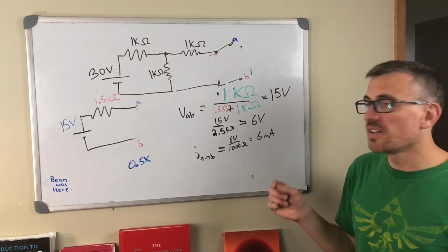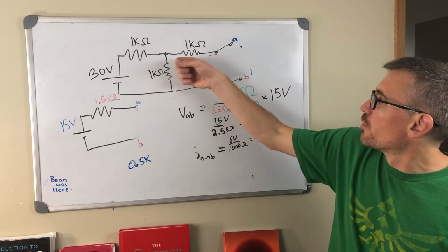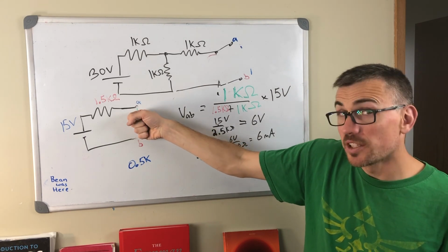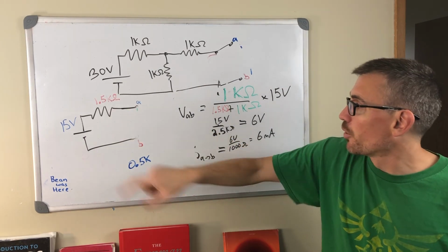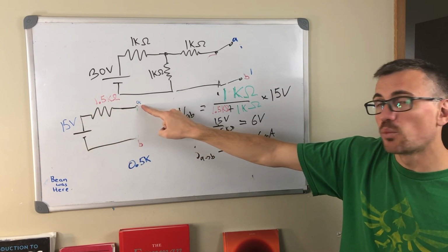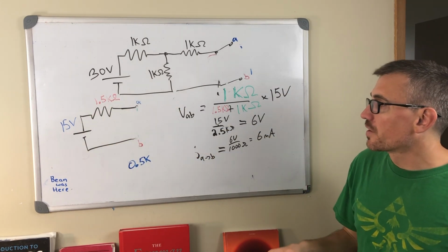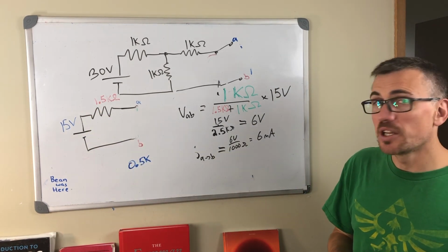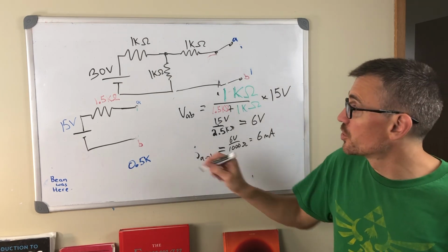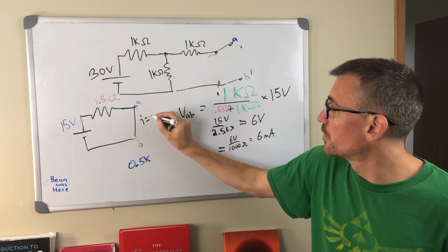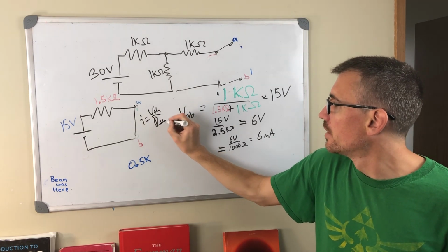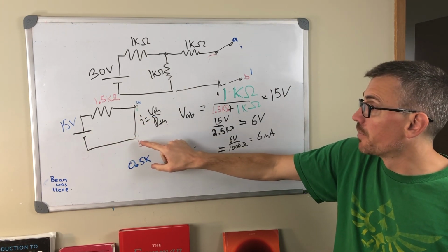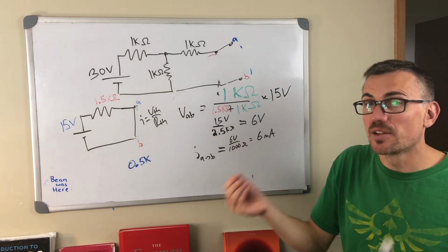Why does it work to find V Thevenin by removing the load and calculating the voltage? Well, if it's equivalent to the circuit, if that's really true, I can pull that out, and that is effectively what V Thevenin is. How does it work that I can scale all the voltages to 0? Well, that's exploiting the linearity of the equations of Ohm's law. Why does it work to short out the current and measure I is equal to V Thevenin over R Thevenin? Well, that works again because whatever I put between here, these two quantities are independent of it if the Thevenin theorem is true.